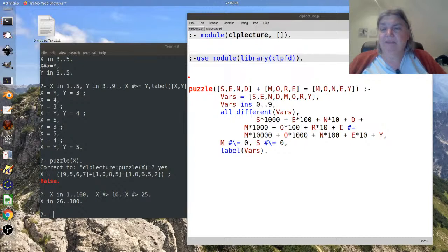Startup is the period when the pressure is less than 100. During startup, the temperature must be maintained between 150 and 250. And during run, the temp must be maintained between 200 and 400.